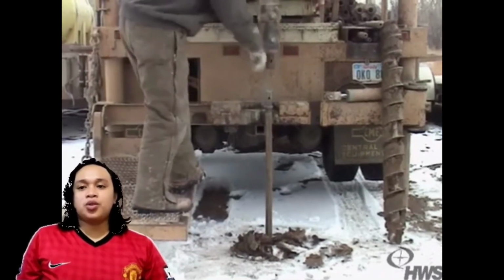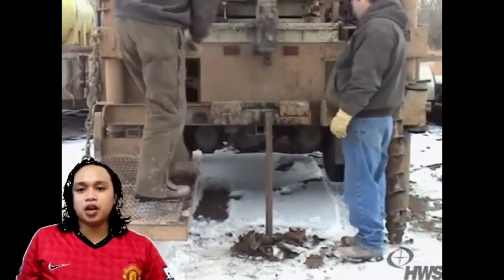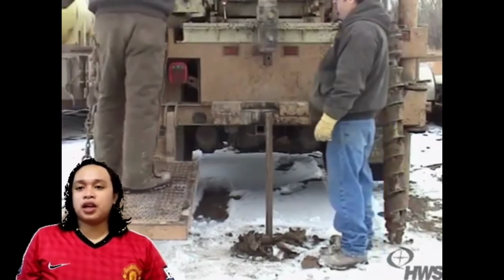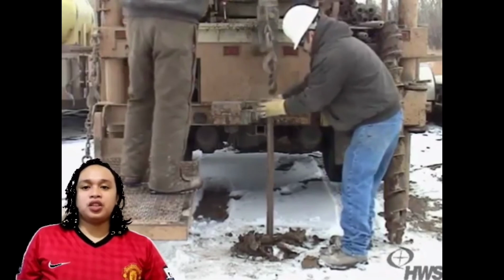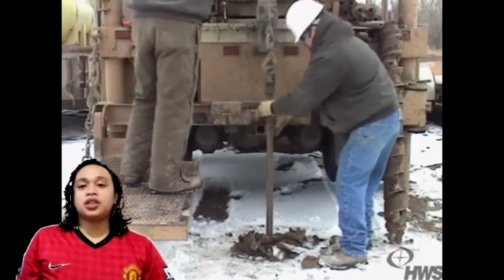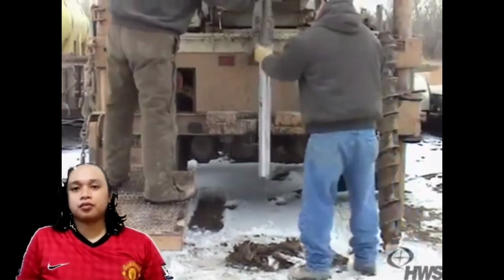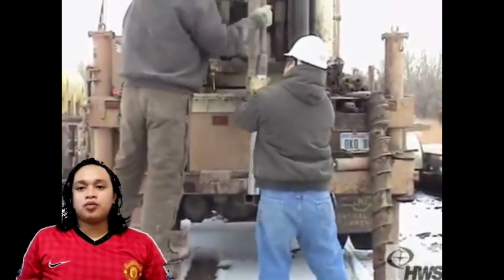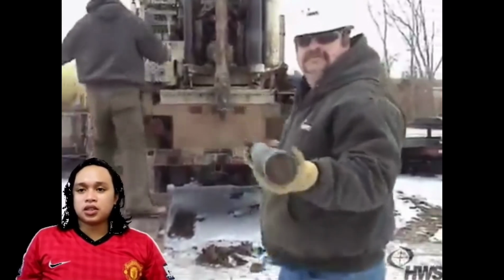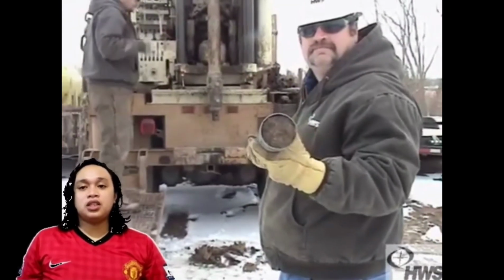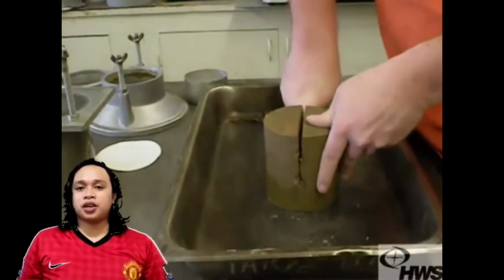As the blows are applied, the split spoon sampler will penetrate into the ground, and the first mark, the 15 centimeter mark for example, on the drill rod approaches the straight edge. Count the number of blows required for the first 15 centimeters, the second 15 centimeters, and the third 15 centimeter mark to cross down the straight edge.